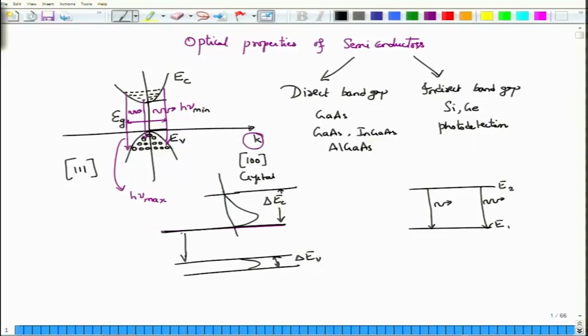Of course, the region in between is the energy gap, okay, and the maximum transition that you can now have will be the one that would go at the top edge of the conduction band, where there is a spread because of the temperature. So, this is at T equal to 0 degree Kelvin. So, this is the transition that can happen, and therefore, h nu max will be the energy difference from the top. So, this is EC, this is EV.